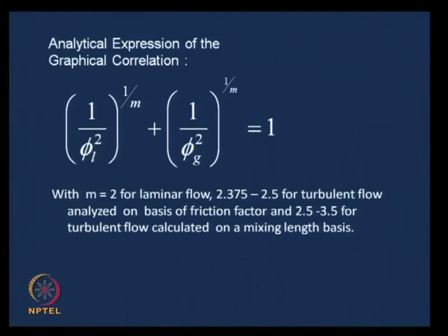Fine. Now, before I proceed, I would just like to stress the things which I had told you: when you are using a correlation you must also know how accurate it is, that is also very important. Okay. So, now let us take up the case of the annular flow pattern. This is the most common example for a separated flow situation, is it not?